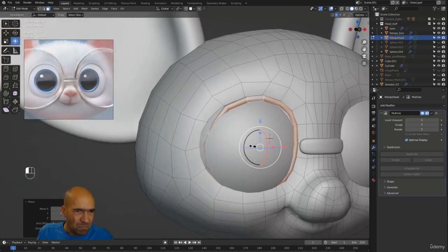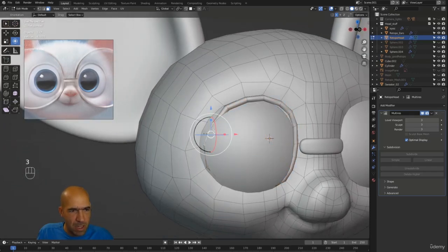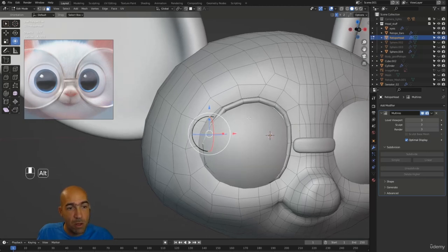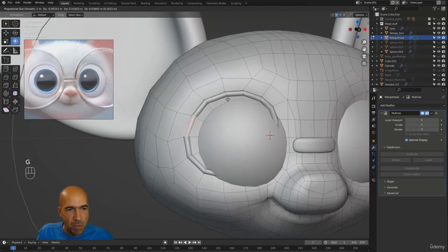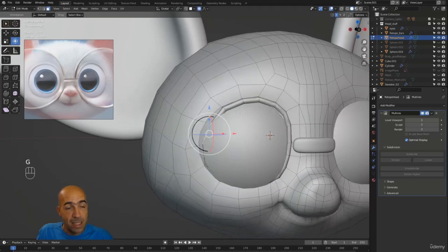And then if we want, for example, to move this with the surrounding polygons also, without going to sculpt mode, we can do that here by pressing this here, proportional editing. Let's try that. I don't use it that much, but in this case may be useful. So I'll press this proportional editing, and when we start moving with G key, the proportional editing is too big.